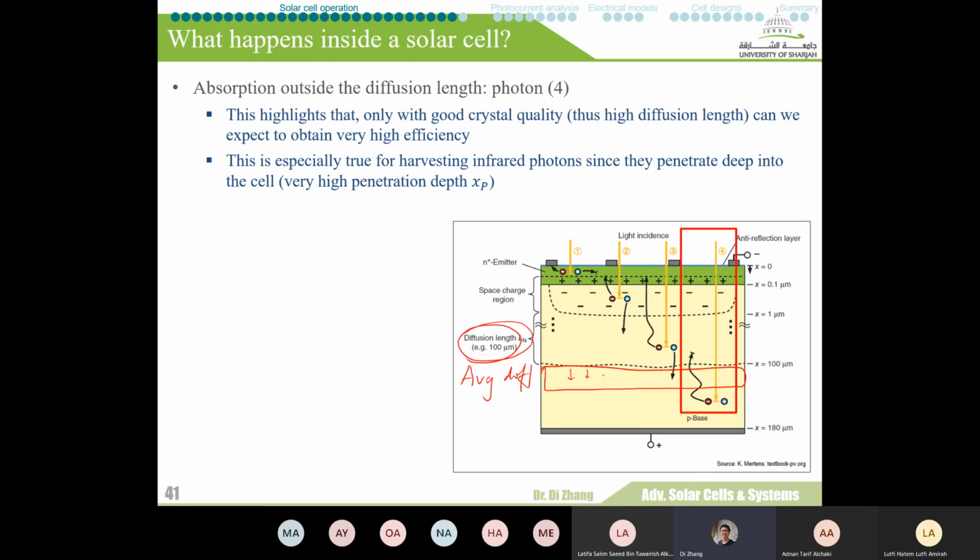Silicon typically has a relatively small recombination loss compared to other kinds of materials. Later, once we talk about other generations of solar cells, you are going to see that the diffusion length becomes more critical. But for the silicon case, even if you increase the thickness beyond the diffusion length, the additional loss is not going to cause you a lot of headache. It's still relatively efficient. Okay, thank you. Yeah, no problem.